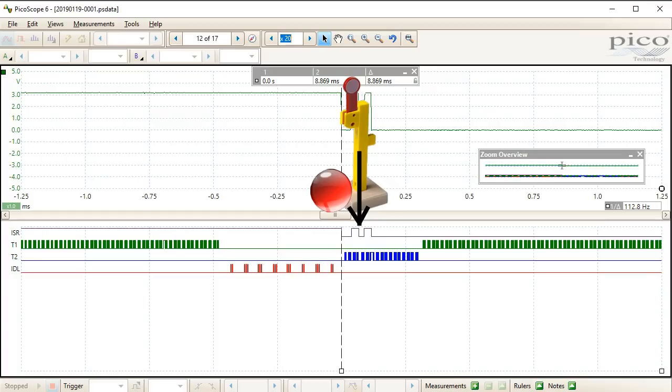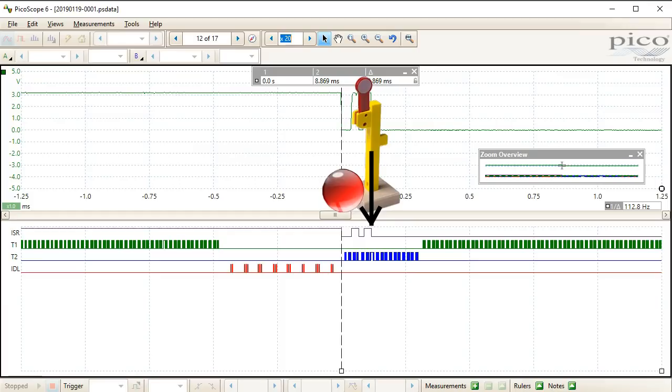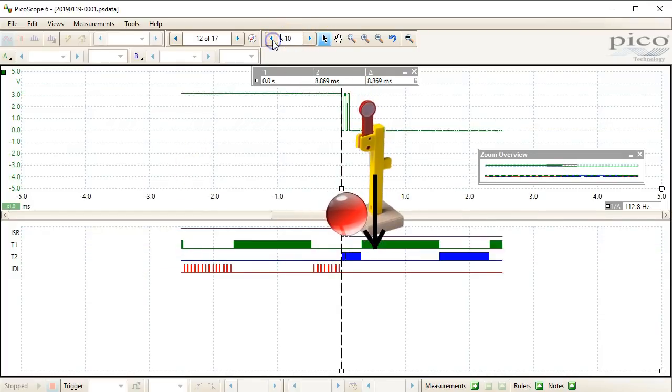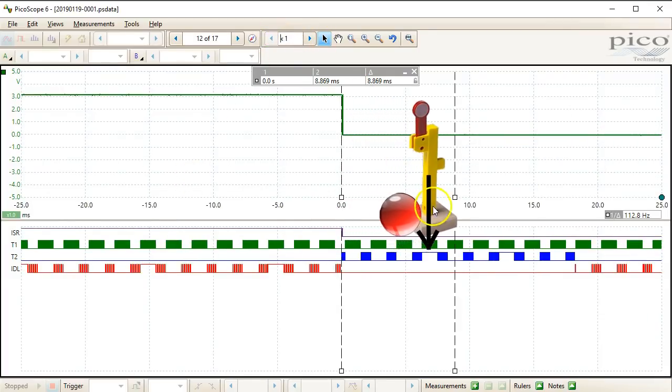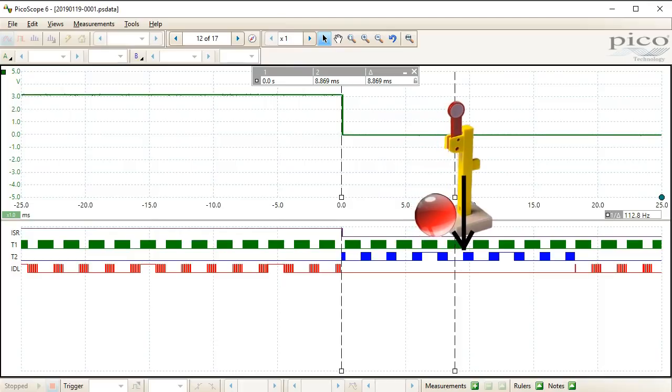The third bounce caused the GPIO ISR to signal the semaphore again, but this time the semaphore already had one token and could not accept another because it was configured as a binary semaphore, with the capacity to hold at most one token. The Blinky2 thread kept running and looped back to the top of its while(1) loop and called the semaphore wait operation.